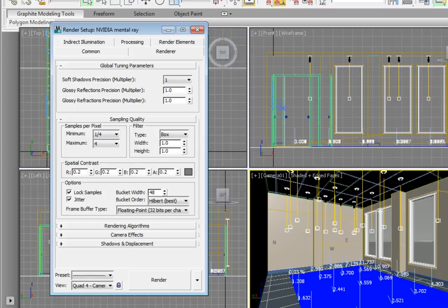These values determine whether an image is undersampled, 1/4 or lower, or oversampled, 1 or higher. Undersampling, combining multiple pixels into one sample, can speed up rendering at the cost of image quality. Oversampling, dividing a single pixel into multiple subpixels, can increase image quality at the cost of rendering time. By balancing the two values, we can achieve a high-quality image without sacrificing too much render time.